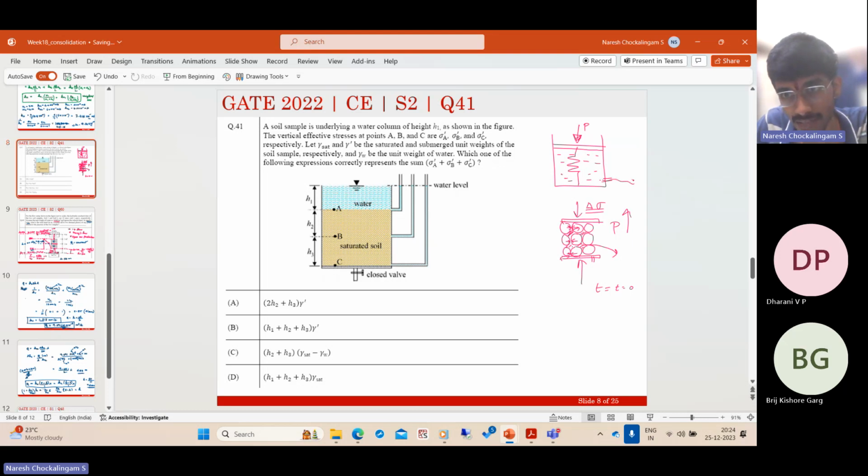But if you allow drainage, under the action of this applied pressure, water will flow out, and at some point, as you allow drainage, this piston will move down and it will compress the spring. At some point, the force K times delta X, the deformation of the spring, will equal the applied force, and this drainage will stop because you have pushed out as much water as you want. Now the force is taken only by the spring.